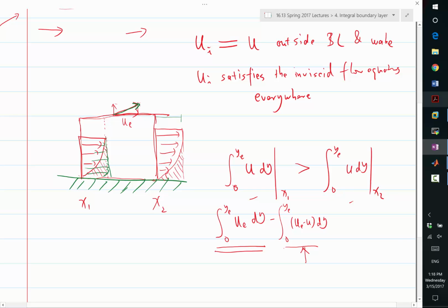And also the velocity profile here is also constant. By constant, I don't mean exactly constant because there are some variations in the Y directional velocity. But the resulting variation in the X directional velocity has to be much smaller than the variation in the red, the true velocity profile. As a result, the imbalance between the mass flux in the inflow and outflow of the inviscid equivalent flow has to be much less than the imbalance of the true flow field.